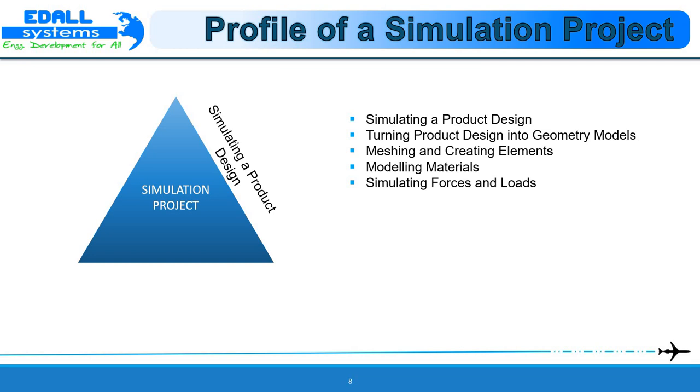Simulating forces and loads. The finite element analysis tests a particular model's reaction to particular loads and constraints imposed as boundary conditions. Loads are environmental factors such as force, pressure, temperature, and voltage. Boundary conditions are described in terms of degrees of freedom and are the directions in which the edges of the model are free to move in 3D space along the translational, that is straight line, or a rotational path.